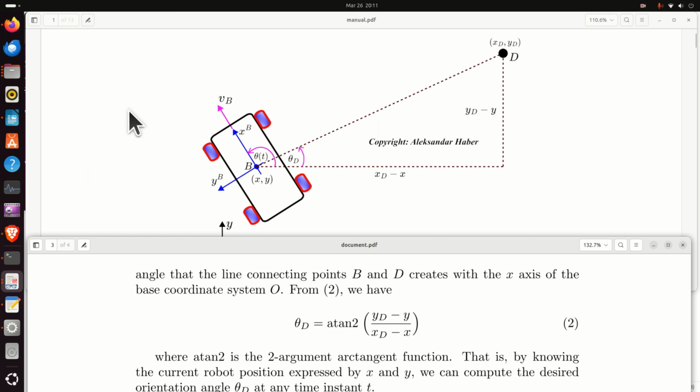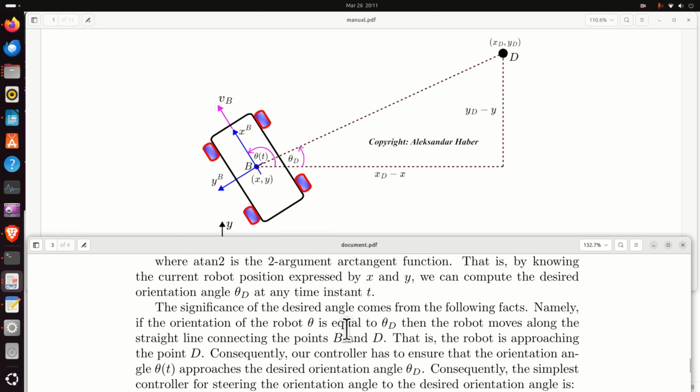It can only return an angle between minus pi over 2 and pi over 2, and consequently we need something else that will take into account where our point is located. That is, we need to take the quadrant of the unit circle into account, and this atan2 function will return the proper, correct angle that can be from 0 to pi or from 0 to minus pi, and always use atan2 in robotics applications.